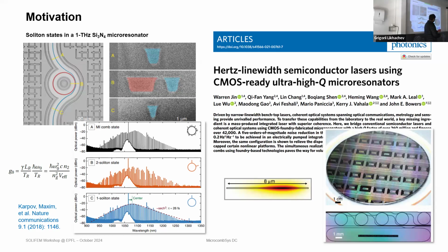The whole resonators are pretty big. This is almost 1 millimeter. Here you see 10 micron. This is 1 millimeter. So these parameters need to be noted when you design such devices, and primarily it comes from the estimation of bending loss.